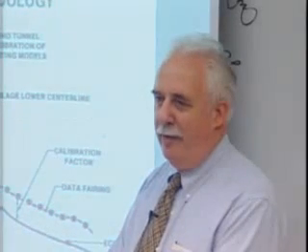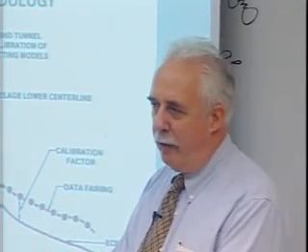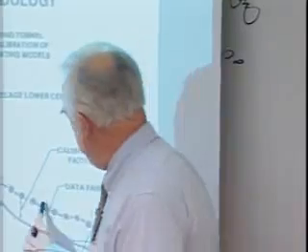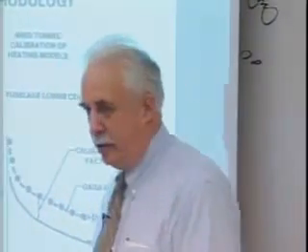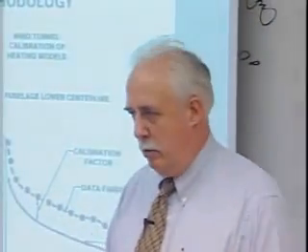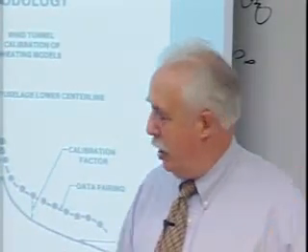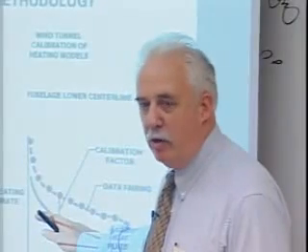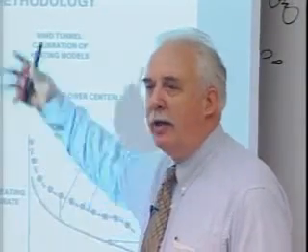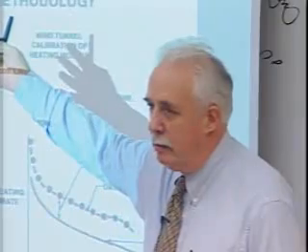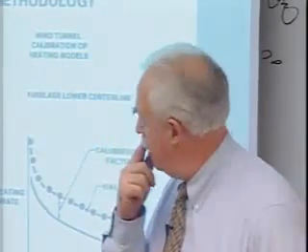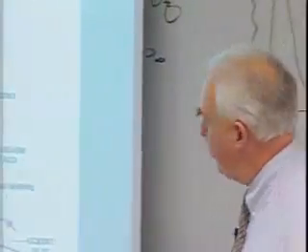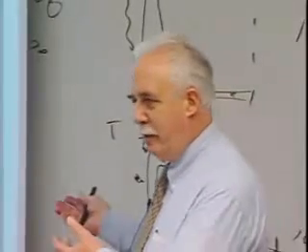But I assume, well, whatever I don't know in a wind tunnel, I don't know in flight too. Okay, but I take this analysis, which can include the chemistry, all the nice things that go on in flight. So I calibrate it to wind tunnel, which is basically an empirical flow field now, and I take that to flight. Works pretty well, really does. Okay, better than my normal shock Reynolds number that I gave to the trajectory guys.